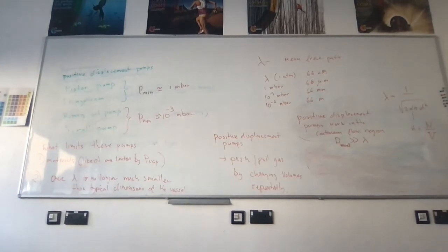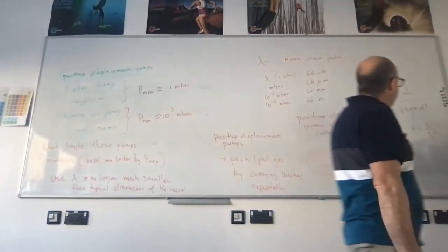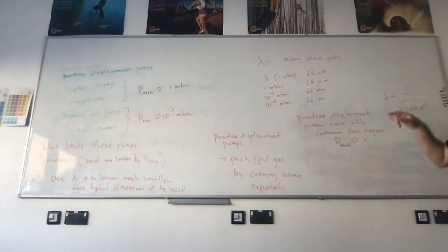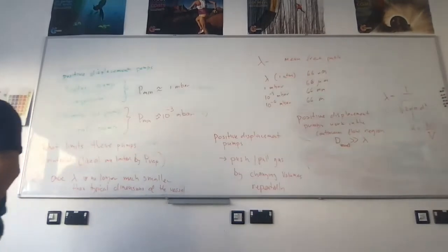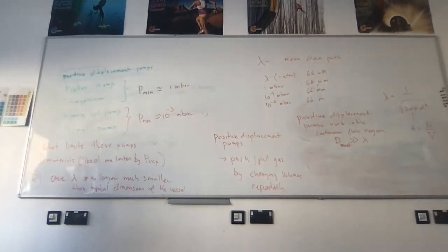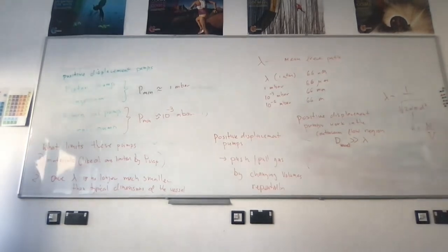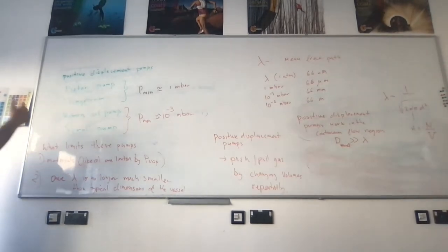Increase temperature. You can increase the temperature. What's that going to do? We're just going to have to deal with more collisions, the vapor. Yeah, actually, if you remember, if we look at this here, there's nothing here which is temperature dependent, right? Because there's a density, which is what it is. It's just a function of pressure and volume. Okay, I mean, you could change it a little bit, but it's not going to affect your lambda much. So it might slightly increase your pumping speed, but then again you'll go down to 10 to the minus 4 and you have no collisions.